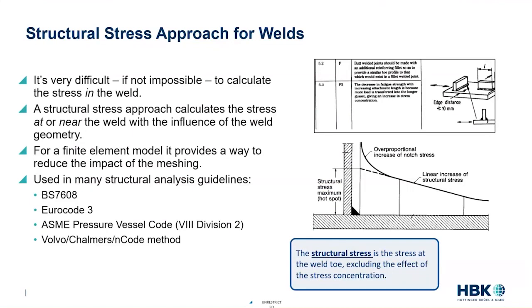That's really what it is. So here we say that it's the stress near the weld or basically extrapolated up to the weld. But what we're trying to characterize is a normalized load at the weld failure location. And we can do this in the test environment with things like strain gauges near the weld or maybe in front of the weld and extrapolating up. In terms of finite element models, we have a variety of approaches to get structural stresses as well. And we'll see two of them today that we're using. But the goal here is to get a stress that's repeatable, is not that mesh sensitive, and I can go in and use that to characterize my fatigue behavior.